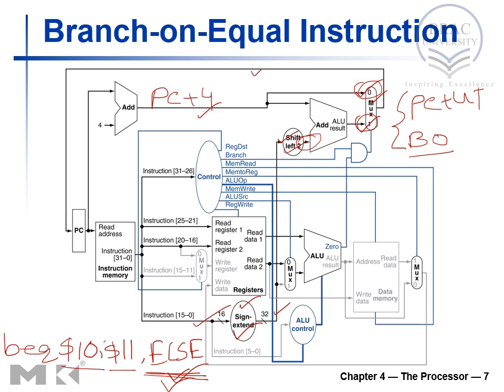So the link that is going to the program counter, replacing the previous value of program counter, can have PC plus 4 plus branch offset, or PC plus 4 in case of sequential execution. The control unit through this AND gate selects which one should go to the program counter.